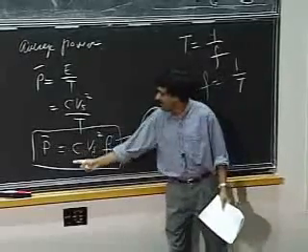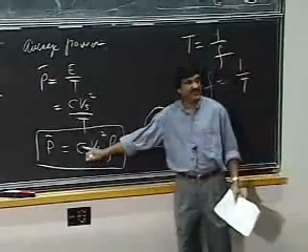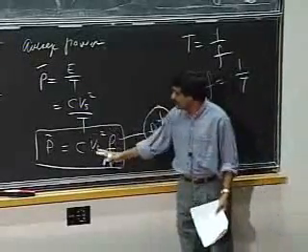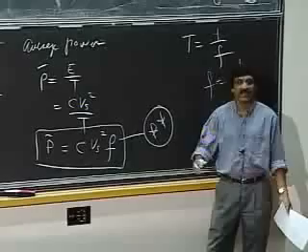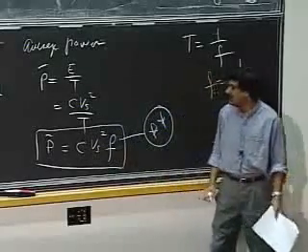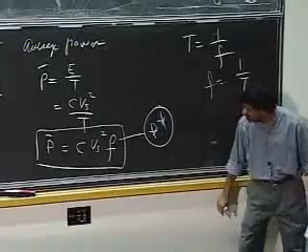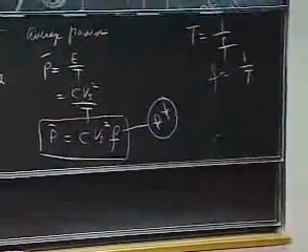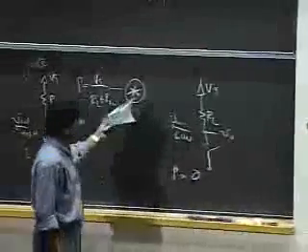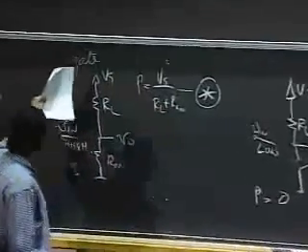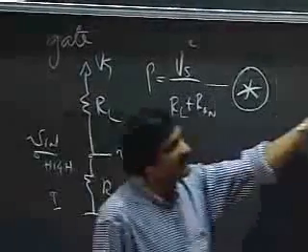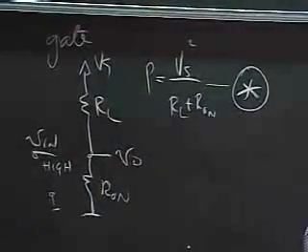And similarly, the average power also relates to the value of the capacitor. If C is larger, I dissipate more energy. And in the same way with the voltage, if the voltage is higher, then the power in that period, or the average power, relates to Vs squared. So spend a few seconds staring at the two expressions. This power here relates to just the connection between the power supply and ground, and that power there relates to charging and discharging capacitors.